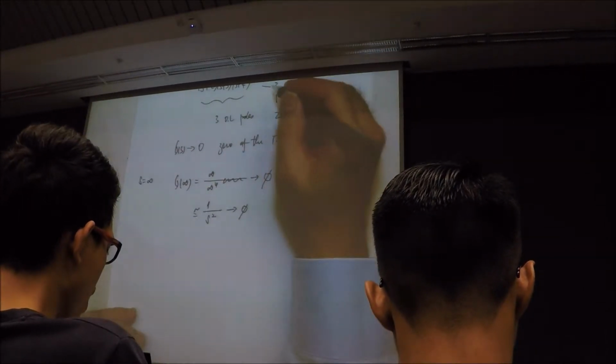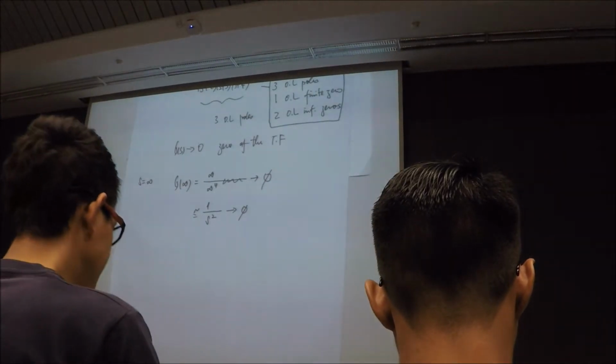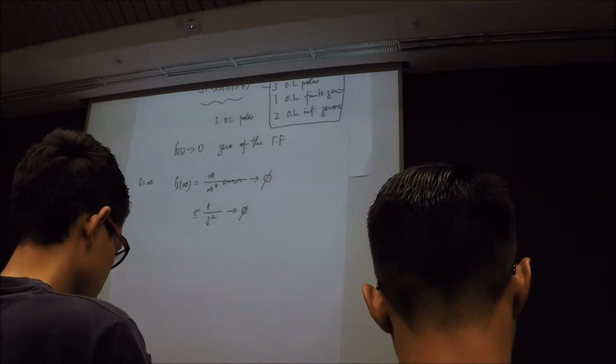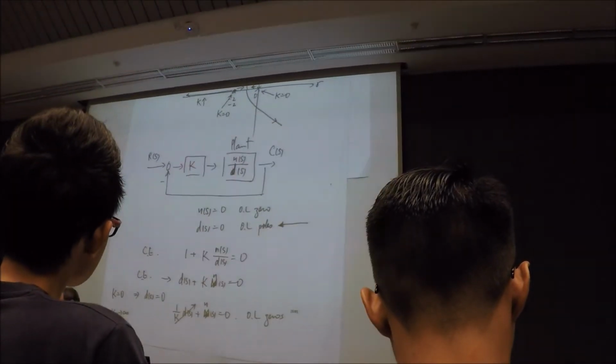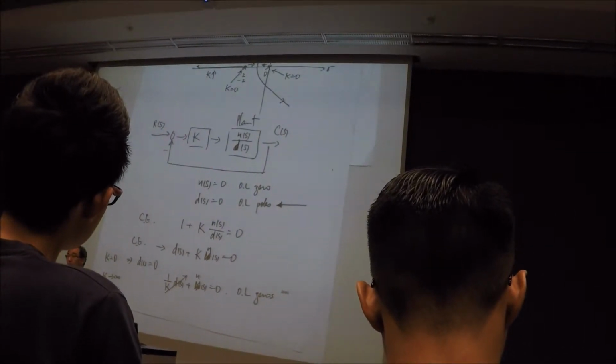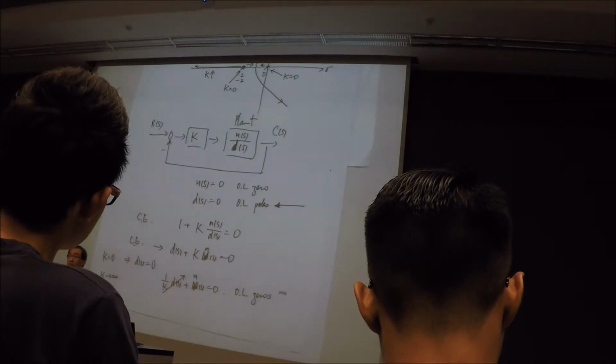Okay, so at the end of the day, basically in the root locus plot later on, you will see that that is why it makes sense. When we come back to talk about this, you have open loop poles, and open loop poles will go to open loop zeros. So it depends on the transfer function.